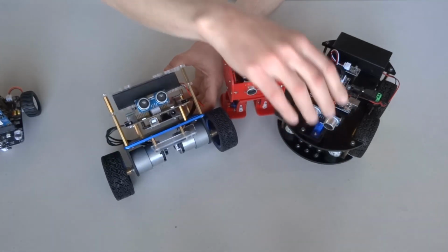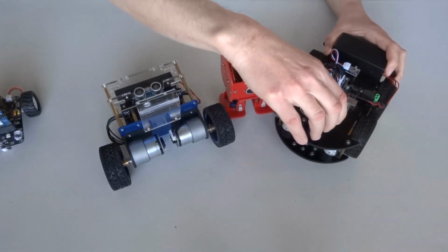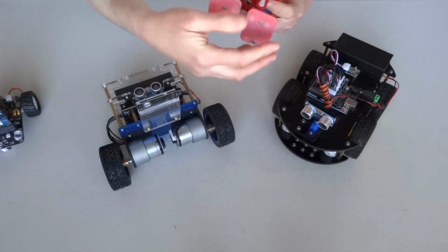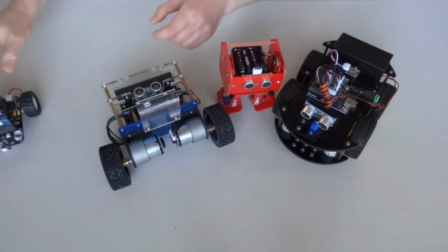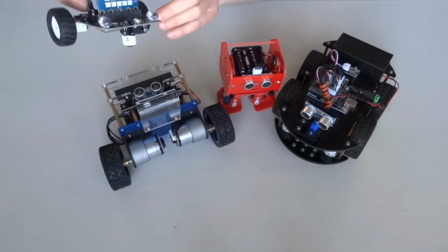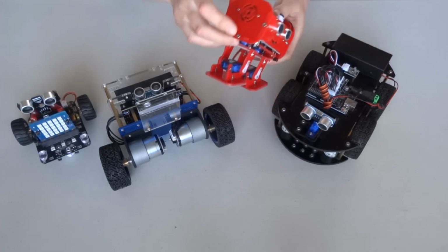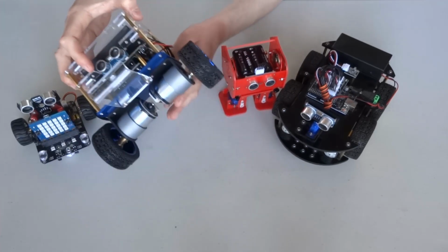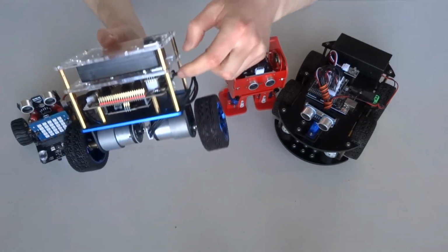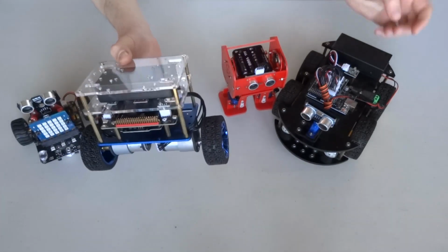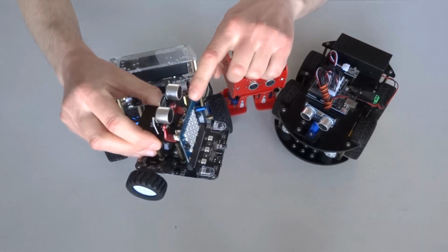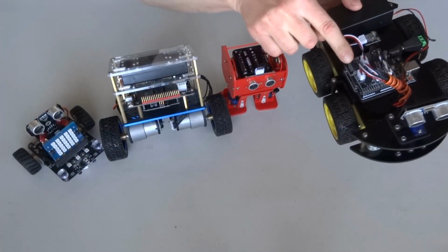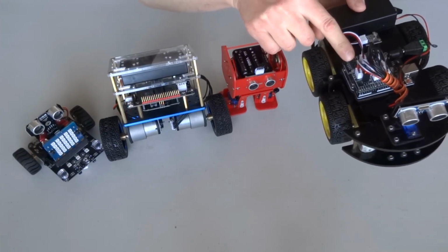As you can see, the robots typically will have sensors, motors, in some cases servos, controlling a variety of parts, and they will have LEDs that can be used to display status, speakers, and typically some form of communication, as is the case of this Bluetooth LE module on this robot, the Wi-Fi and Bluetooth LE within the ESP32 of this one, or the optional Bluetooth Classic that can be connected to this robot.